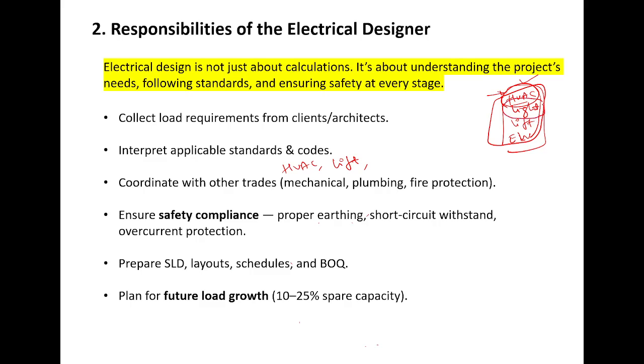Similarly, you should go with the lighting load. You should coordinate with your sustainable development department and your architect on what procedure or technology they are using to minimize the use of light in daytime, so you can use a high demand factor in daytime.